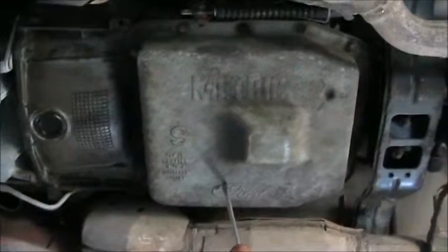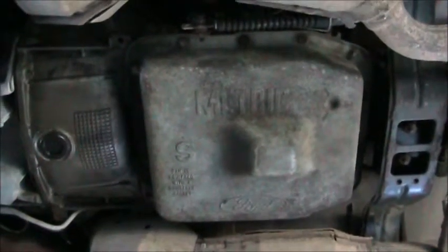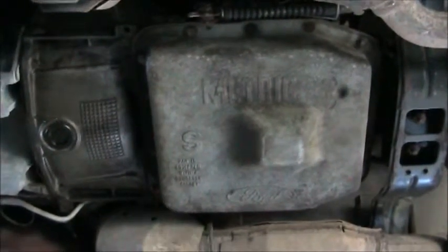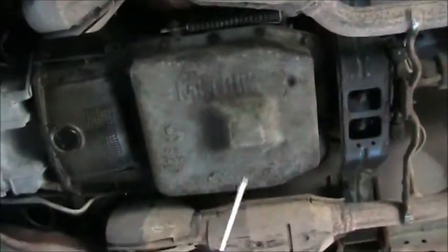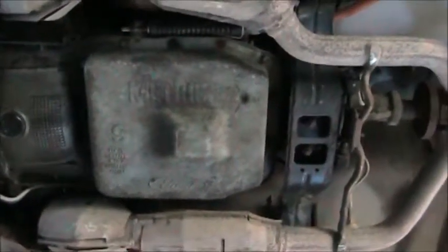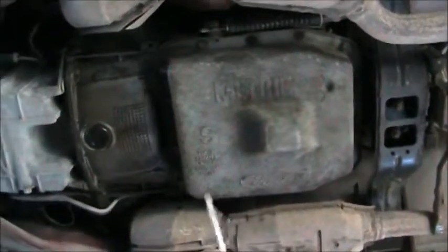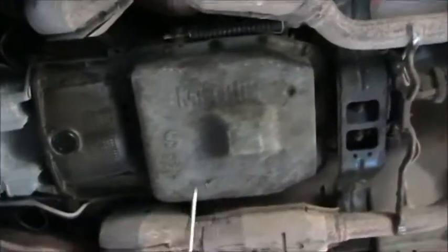Next we have the transmission pan. This is the transmission pan. In a previous video we demonstrated a proper servicing of an automatic transmission to remove the pan, replace the filter, top the transmission off with new fluid, and above that fluid level there's going to be a valve body. That valve body controls all the fancy hydraulics inside the transmission that allow it to shift automatically. Above that there's going to be input shafts, planetary gears, clutch packs, and bands.